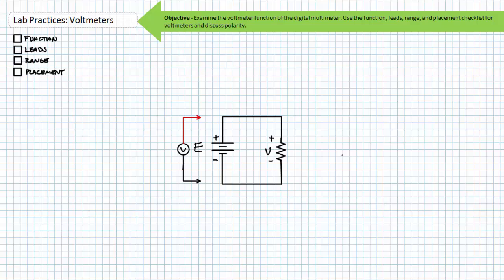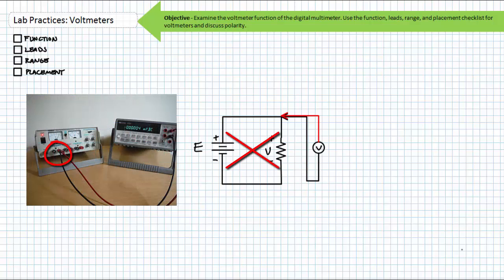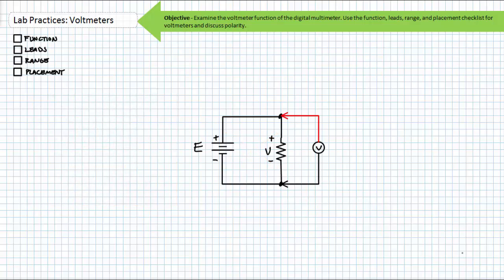The takeaway point from this whole excursion is that voltage measurements are across something, and would not make sense if both leads were placed at the same point. If the voltmeter is supposed to be determining the difference between the high lead and the reference, and the high lead and reference are at the same spot, there is no difference between them because it's the same spot. Voltage is across. Voltage is a 2-point measurement.